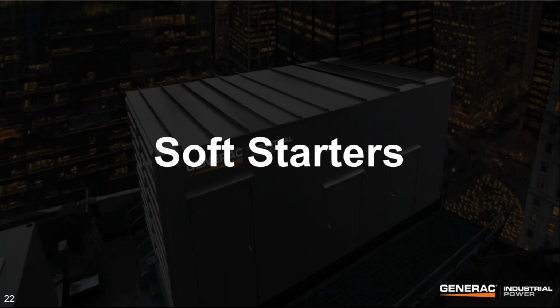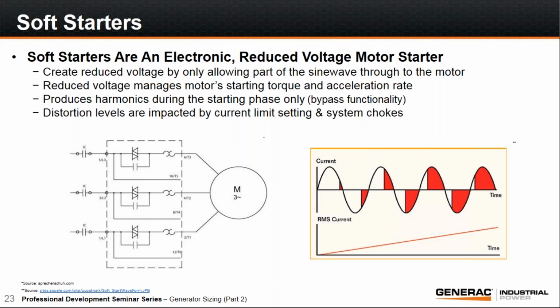So one of the things we can do to help the size of the genset when we're starting big motors is we can limit the LRA, locked rotor amps. One of the devices that's used quite a bit today to do that is called a soft starter. What soft starters do is they limit how much voltage the motor sees, and it does that by gating the sine wave and only allowing a piece of the sine wave to come through. So what they can do is start off with just a very small piece of the sine wave, very low voltage, and ramp voltage up until you get the complete sine wave being applied to the motor.